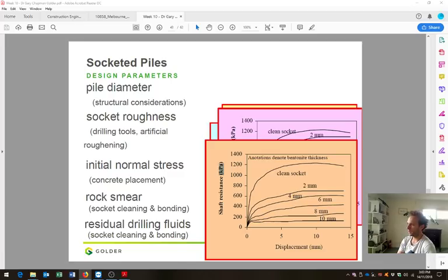So Arthur, when determining serviceability limit state load for a group of rock-socketed piles, if the factored structural capacity is less than the unfactored shaft resistance, are we supposed to use N piles times RDS for serviceability limit state? Yes is the short answer, but I would write this as a literal sentence in an exam. I would write serviceability limit state equals maybe 15 meganewtons. However, the structural limit state was only 9 meganewtons, therefore serviceability load should be limited to no more than 9 meganewtons. That would be a perfect answer in that respect. But yeah, you're right.